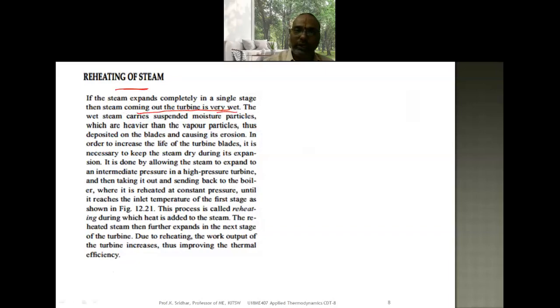So I told you that if the wet steam is leaving the boiler, when it is hitting the turbine blades, automatically erosion problems and corrosion problems and pitting of the turbine blades will occur. Due to which the turbine life will be reduced. So that's why, because it basically results in erosion problems, the life of the turbine is also reduced.